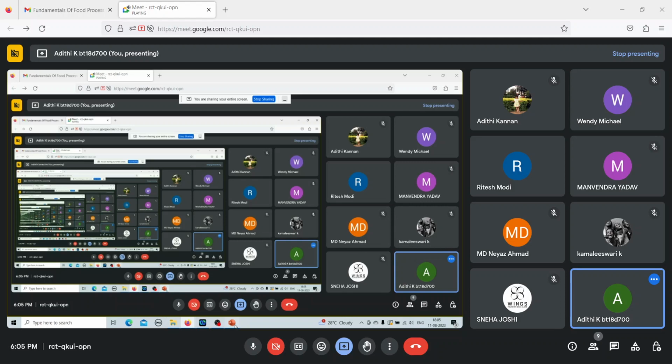What happens in lumped parameter analysis is that you lump all these parameters into a dimensionless number, which is the Biot number, which is why it is known as lumped parameters. You have the Fourier number, you have the Biot number. All these are lumped parameters that include multiple parameters together to make a dimensionless number. With these dimensionless numbers, we calculate the temperature of the body at a particular location, which is why it is known as lumped parameter analysis.